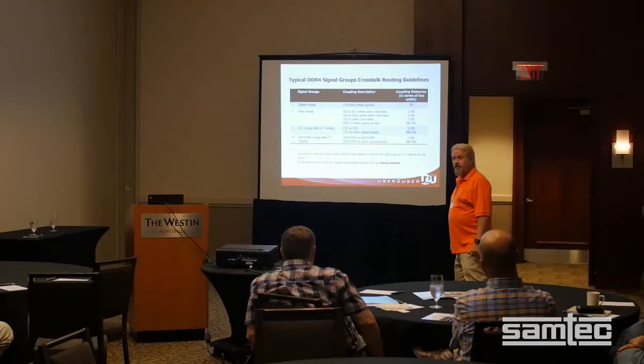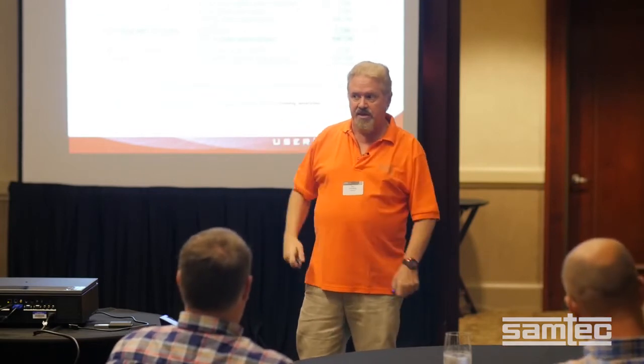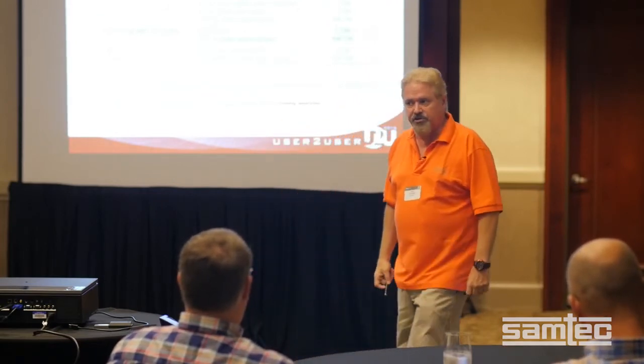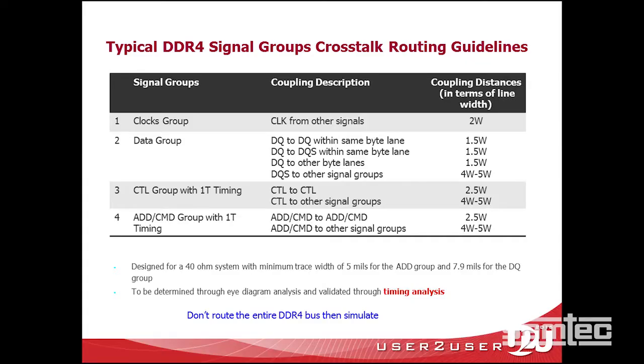So, but if you have a limited number of layers, you'd like to use the outside layers. So if it's a bit longer, the traces on the outside need more space than the traces on the inside. If they're shorter, they can be the same. How do you know this? This you do have to simulate. Because what does crosstalk noise do?